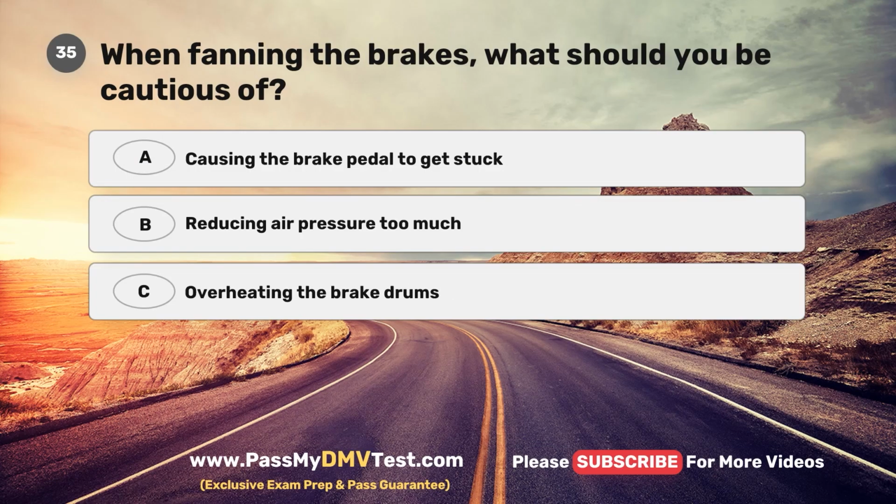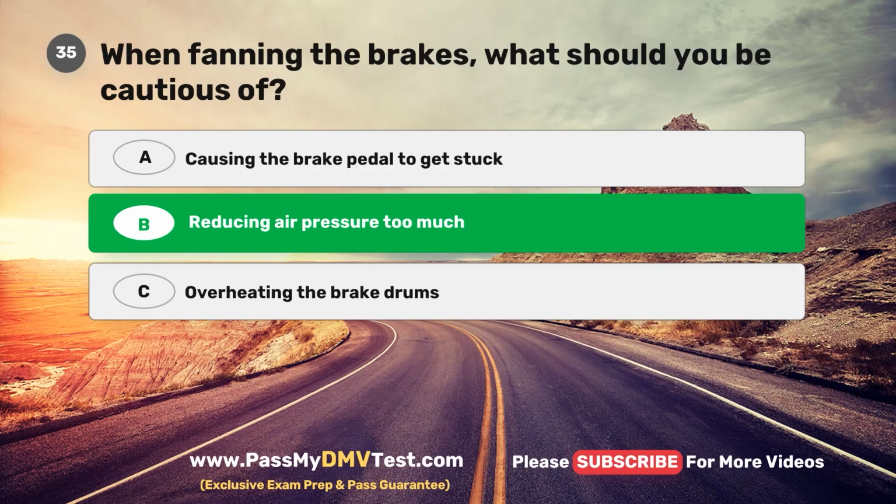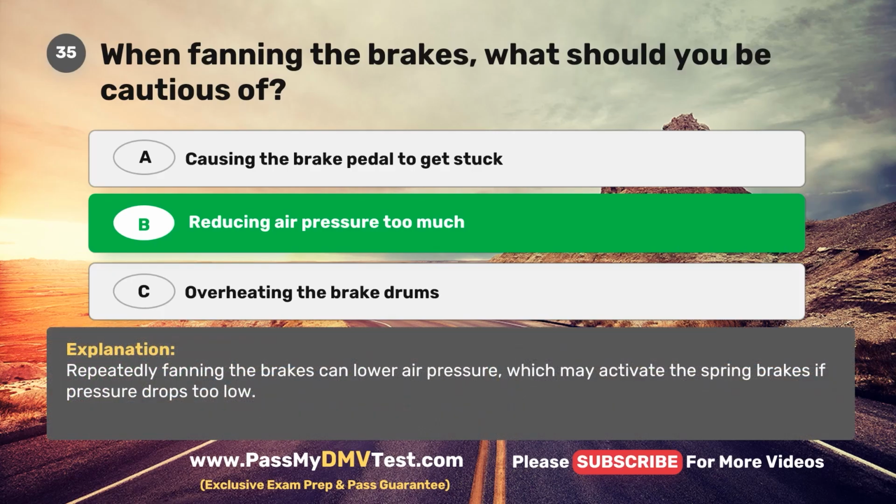Question 35. When fanning the brakes, what should you be cautious of? A. Causing the brake pedal to get stuck. B. Reducing air pressure too much. C. Overheating the brake drums. The correct answer is B. Reducing air pressure too much. Repeatedly fanning the brakes can lower air pressure, which may activate the spring brakes if pressure drops too low.